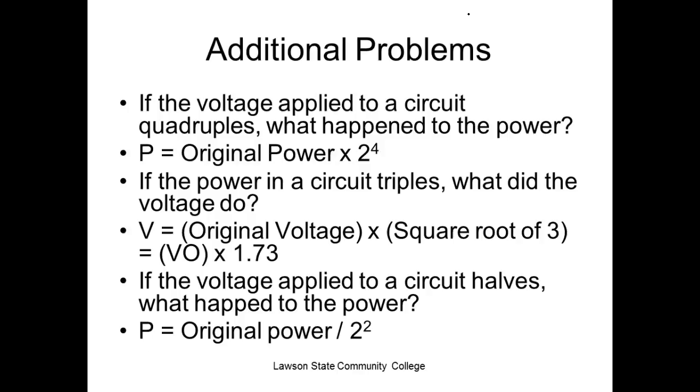But speakers have a lot of wires in them. So like I said, if you got an 8 ohm speaker and you measure it with an ohm meter, it'll probably measure 5 or 6 ohms. Because that 8 ohms is at 1,000 hertz. So if your frequency goes up, its opposition goes up, because speakers are nothing but big old inductors. So that's why you try to,